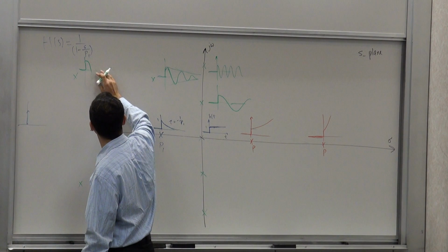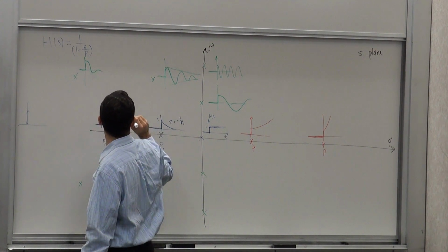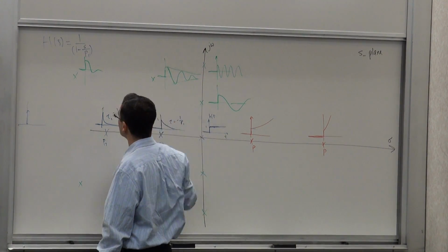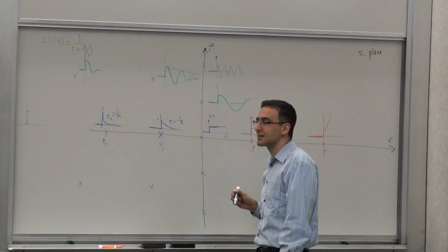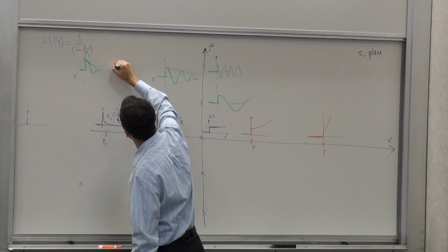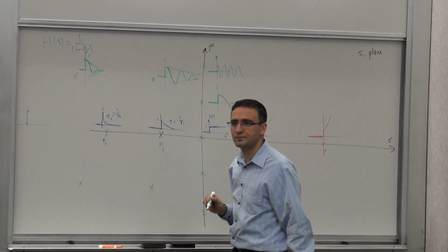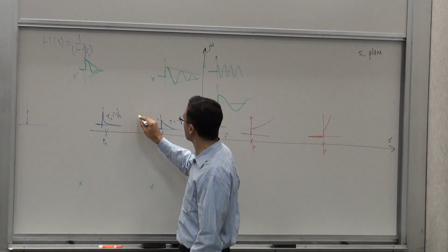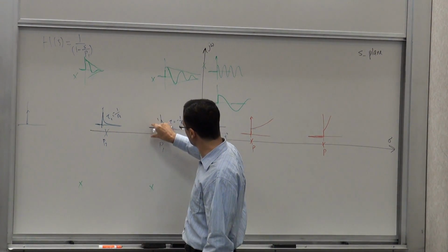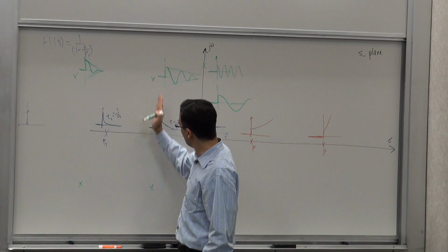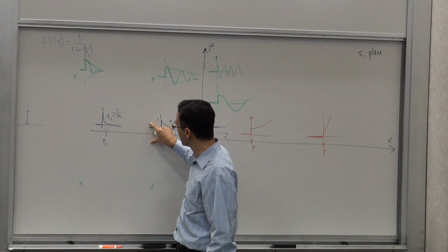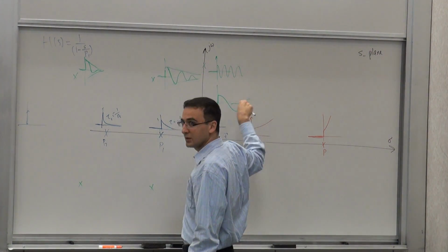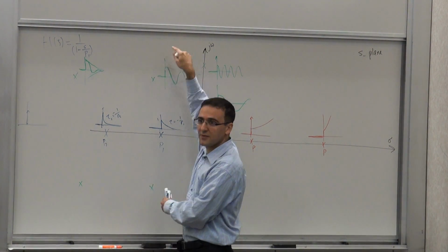It's just more difficult to draw. So the sine part, the cosine part of it will have pretty much the same frequency, but it will decay faster. And if the poles were down here, what would you see? They have the same real value, but a smaller imaginary part. The decay rate would be the same, but the sine would become slower. And if they were farther out, the sine becomes faster.